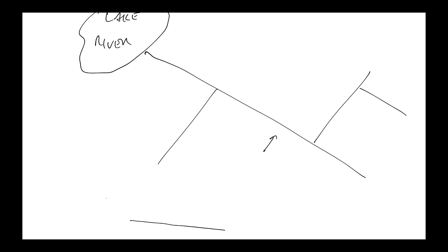Some bottom slope, very gradual, and along these open channels there are these regulating structures that can be adjusted, and those regulating structures are usually positioned just downstream of supply points to so-called secondary channels, and they will also be located along the channels situated just downstream of supply points to end users.